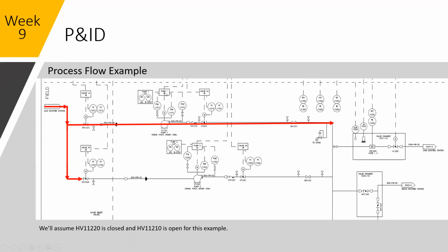Here there is a pump junction box and a pump 1 local control panel that has some hand switches that say jog and e-stop. So by looking quickly here, you can get an understanding of, okay, well, out at the pump, we have some pressure sensors. We've got a pressure 500 mils. We can get a rough idea on how big the piping is coming out of that. So that's 0.5 meter. Typically that would be the inside diameter, I believe.